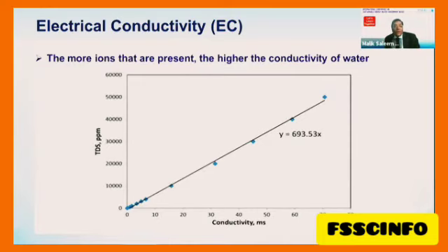And there we have the relationship of conductivity, because the measurement of TDS is by the evaporation process and it takes some time. But in water treatment technology, we can correlate the direct measure of conductivity with TDS almost. If you have 10,000 conductivity, it means you have 5,000 TDS. That is just a thumb rule for you, and the factor may vary from 0.5 to 0.7, depending upon the ionic composition of that sample. It is just for your reference that in water treatment we correlate conductivity and TDS as well.